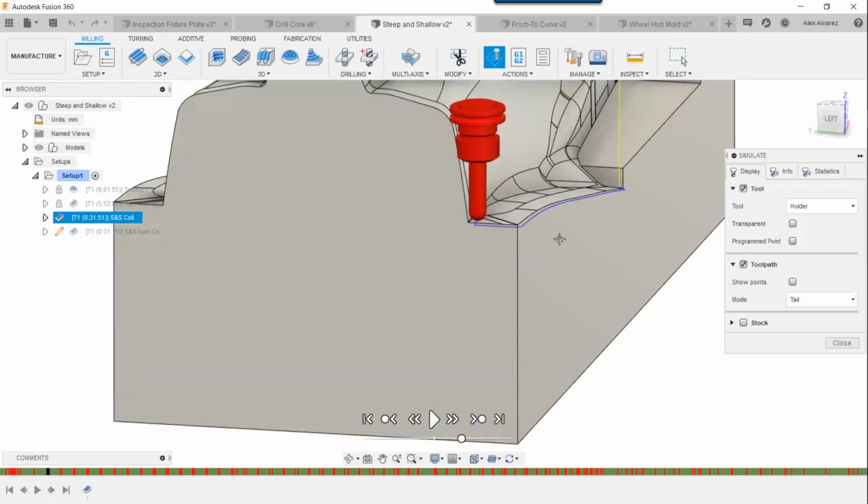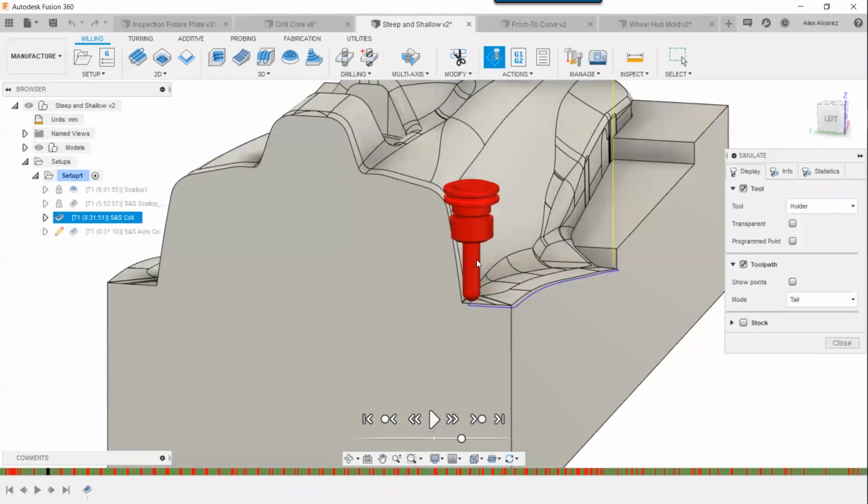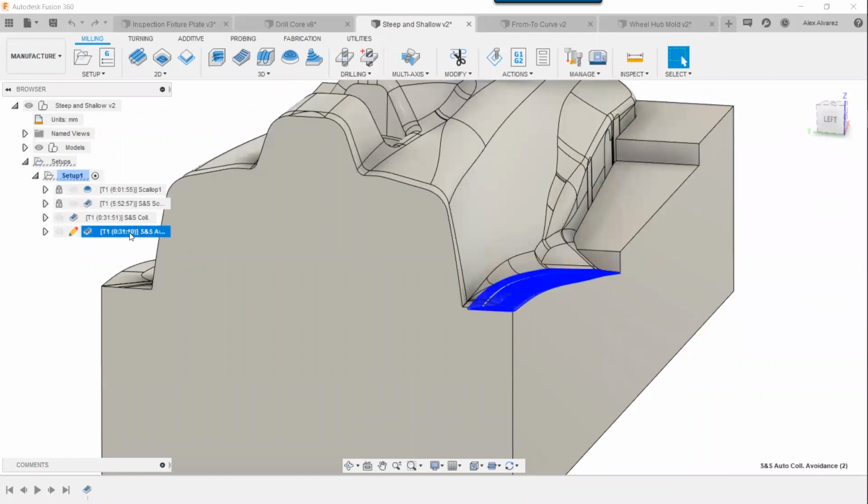Now, again, a couple options. You can swap this out and change it for a longer tool. But if you have 5-axis capabilities, take advantage of that. You want to make sure that you leverage those capabilities, and not only that, get a tool that's much more rigid than something that has a greater stick out length. So I went ahead and modified it. A little pencil shows up because that's indicating that I made a toolpath trim to it. So I trimmed out this section.